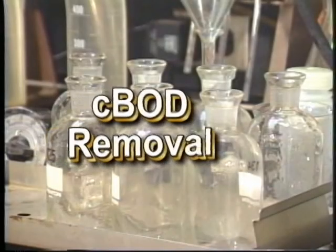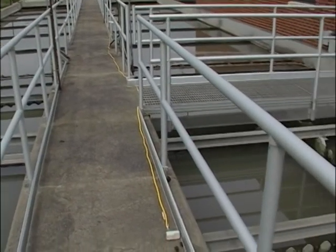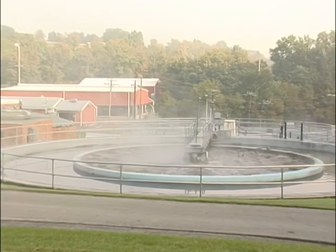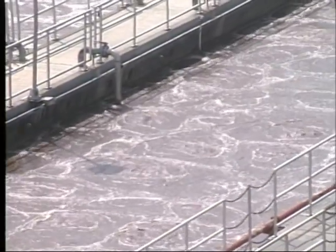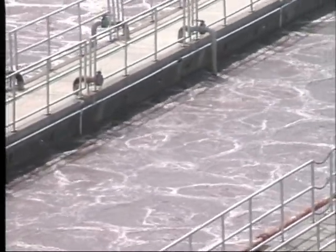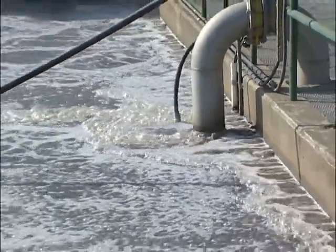Factor number 7, CBOD removal. In order for nitrification to take place, CBOD must be significantly reduced. If we do not have adequate reduction in CBOD, nitrification will not take place. CBOD should be reduced to below 25 milligrams per liter in order to facilitate nitrification.